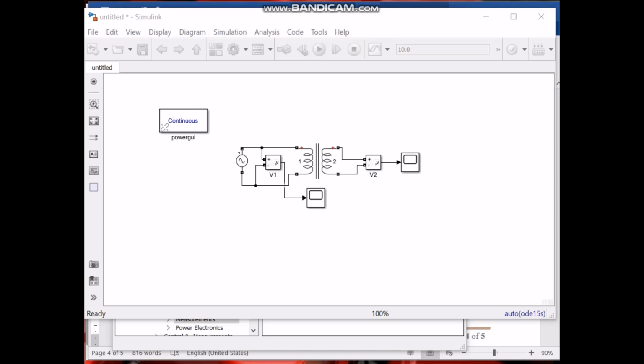So this is why we need to conduct the polarity test and turns ratio test, because if we don't know the polarity, we would make the wrong connections while connecting the transformers in parallel. So this is why it is important to know the polarity. So just like we did in the simulation on Matlab Simulink, the same procedure we do in practice to get the polarity and turns ratio. So nothing is changed. The similar process can be done practically on a real transformer, and we would get the same kind of results.